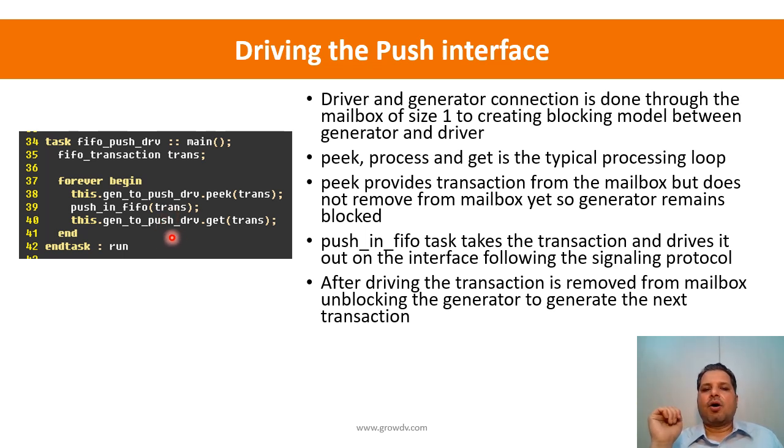We had already seen that in this class, FIFO push driver class, we had a virtual interface which is connecting to the DUT side. So we have two sides to this driver. One side connects to the DUT, and another side connects towards the generator. If you remember that layered architecture, at the bottom there was a DUT, above it a driver, and on top of the driver we had the generator.